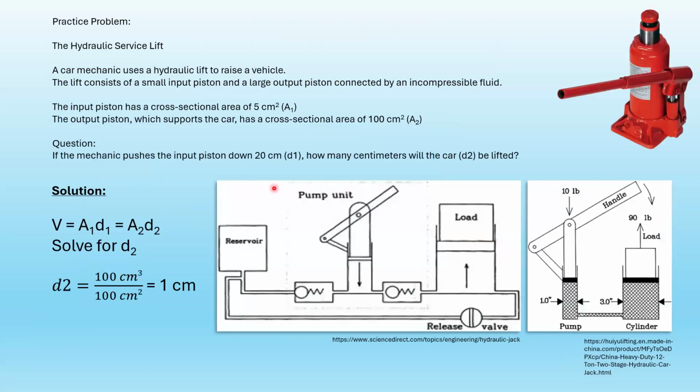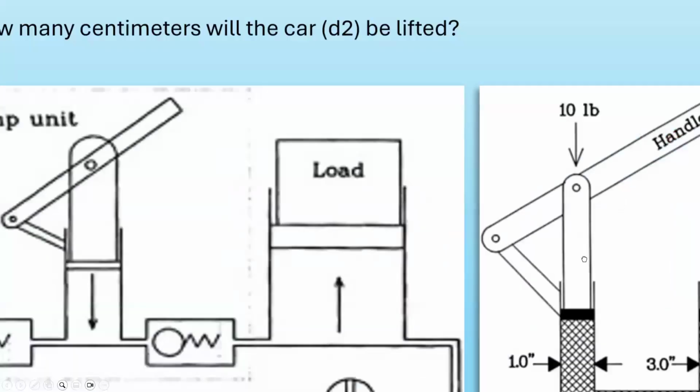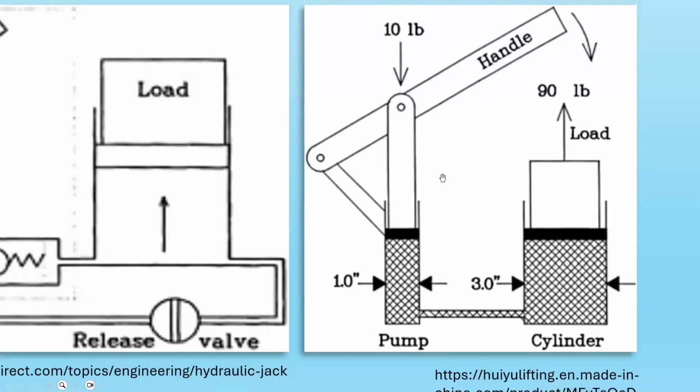And here's the famous last picture, a car jack. What do we have here? It's kind of a bad design, right? Because you push on that handle, this thing goes up. But it's just a conceptual type of drawing. So we have a certain size of piston right here, and a certain size of cylinder. If you pump this one, you move the handle a certain way, and you have to move it more distance for this thing to come up less distance.